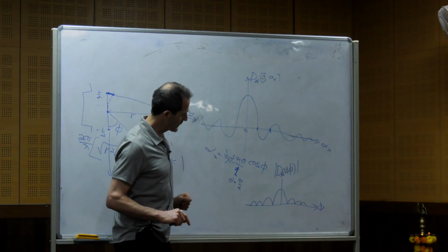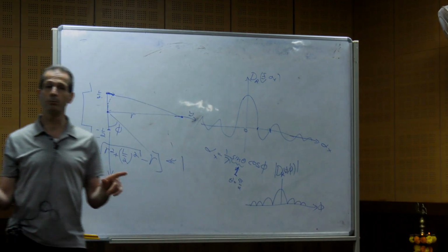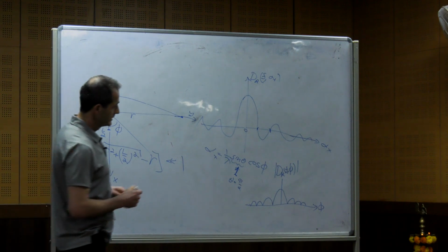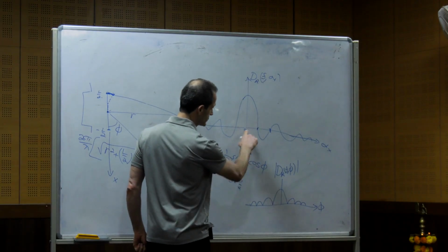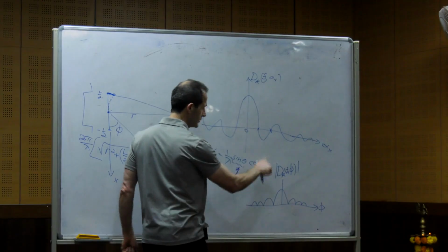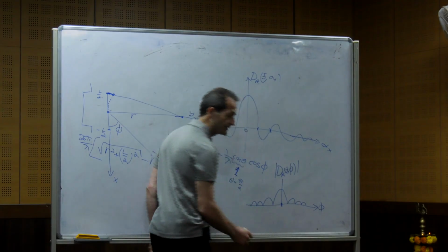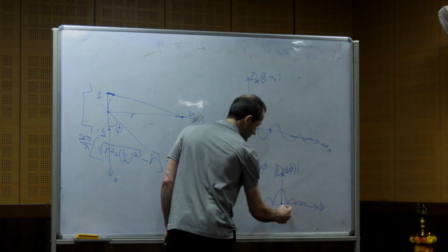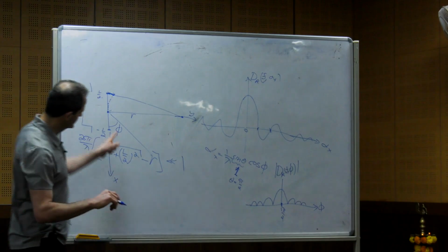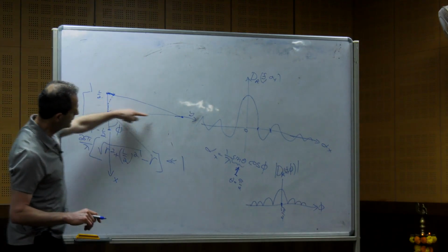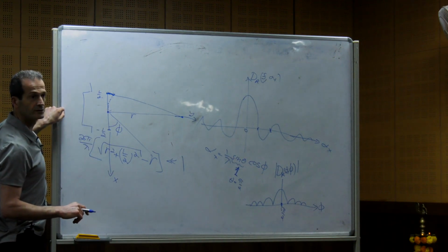which means that we can separate signals that come from different directions based on the frequency. And then, instead of something like that, sometimes we have a polar plot, which is very useful. By the way, when alpha x equals 0, so cosine phi equals 0, what is this? Pi over 2. So it's not 0. And it makes sense, because if the direction is pi over 2, the signal comes from here. This generates the maximum electric response.